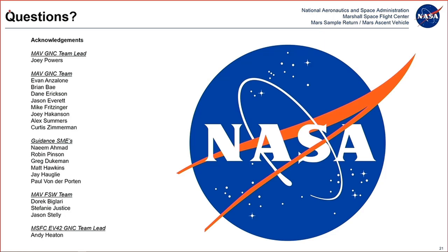We are timing our orbital precession rate for the ERO to come in right at the same time, all the way from Earth. So we're planning that whenever our orbit precesses the right amount, that's when our ERO is going to rendezvous. If we were to just go to the highest semi-major axis possible, we'd get a different drift rate, and in fact, it would pretty drastically change the CONOPS requirement on ERO.